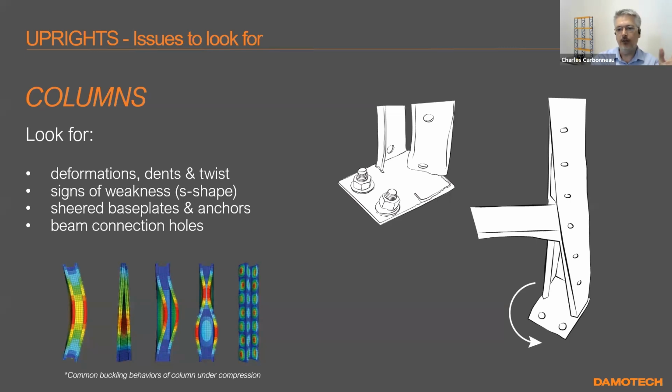And he was asking, what do you recommend in terms of maximum twist? You can find on the web certain references where people put a square around the column, and if it's twisted by half an inch on the footplate, that's the limit. Well, it depends. As a general rule, not bad. If it's a 3x3 cold form column, not too bad. If it's a structural steel column and it's a single column, then we get into a different situation.